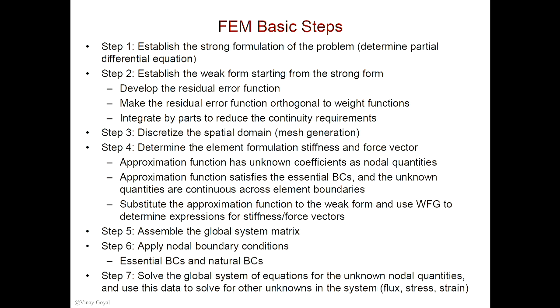We found that when we formulate the elements, it's very painful to calculate all the shape functions for every single element, and the integration over an element can be complicated. So why not just come up with an approach where everything gets mapped to either a square or regular triangle, or a shape that everything is standard. I calculate everything in that standard geometry, and that helps because the shape functions are the same, the integration scheme is the same, the derivatives of these shape functions are the same for every element. And what I've done is I've decoupled the geometry from the problem, and I track the geometry using the Jacobian. Is that clear?